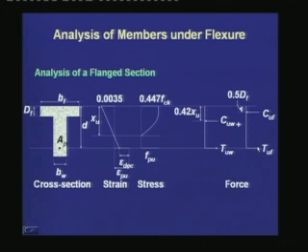The purpose of decomposing the forces into these two components helps us to analyze the flange section properly, where we have been able to identify the individual couples, and we are able to calculate the lever arms for each of those couples.